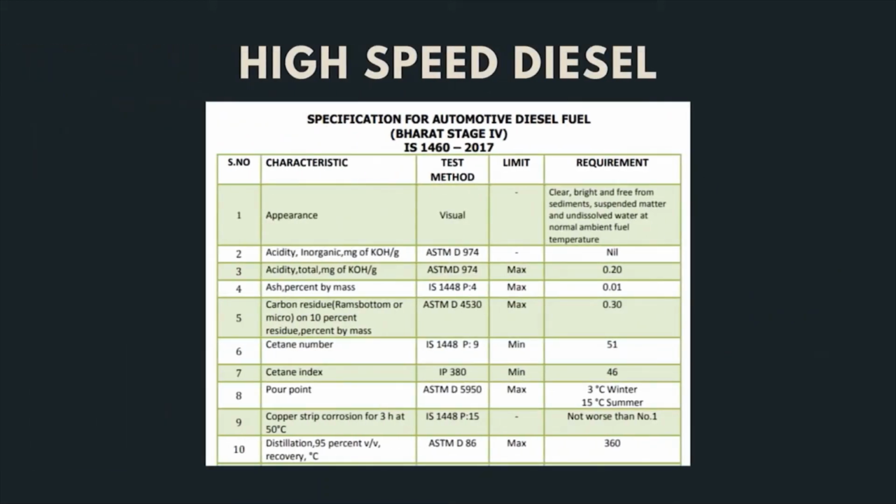The important test for diesel is the cetane number. Just as octane number is important for gasoline, cetane number is important for diesel. Then carbon residue is yet another important test. Then the third important test is the pour point. Pour point is the temperature at which the liquid ceases to flow.